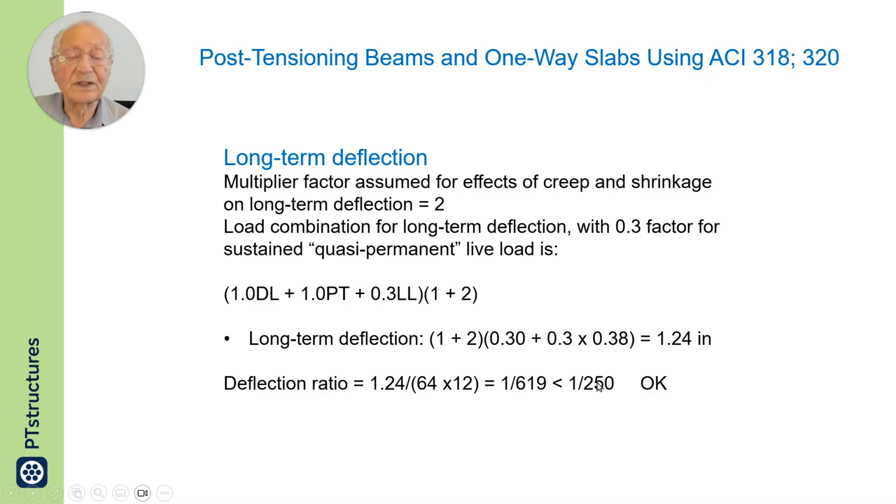I see I have here taken 1 over 250. Actually, ACI says 1 over 240. This 250 is the European code. In any event, it is acceptable. It should not exceed 1 over 240, not 250.